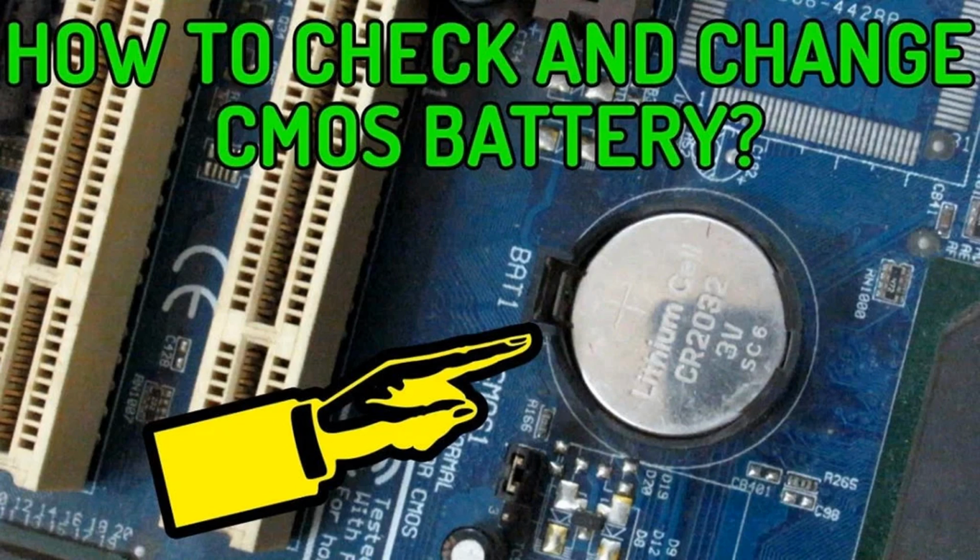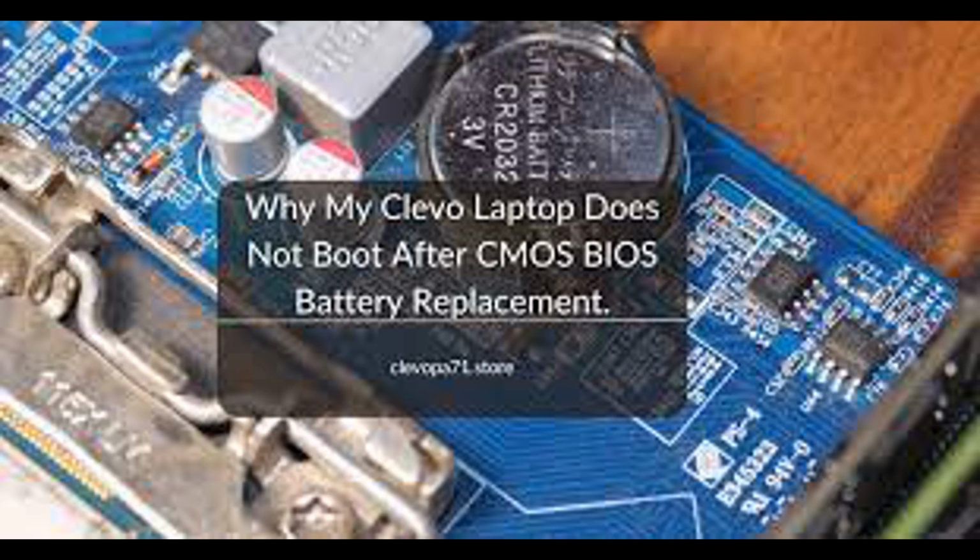Static power dissipation. CMOS logic gates consume negligible power when they are in a static state, i.e., not switching. In the static state, one of the transistors in the complementary pair is off, creating a high impedance path between the power supply and ground. Therefore, there's almost no direct current path between the power supply and ground, leading to minimal static power dissipation. This is in contrast to other technologies like bipolar junction transistor, BJT, or NMOS alone, which draw static current even in the idle state. Dynamic power dissipation. CMOS circuits primarily consume power during switching, known as dynamic power dissipation.